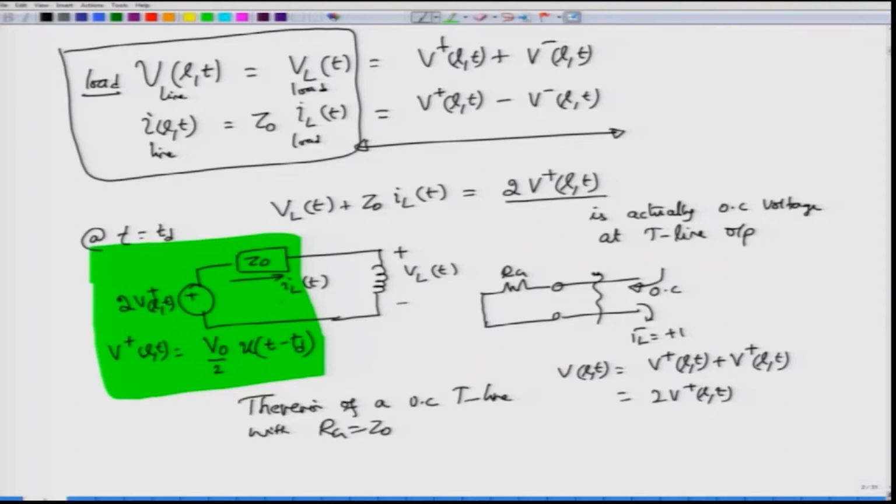How do I do that? Well, this is an inductor. What is the relationship for an inductor in terms of the voltage and the current? For an inductor, we remember that if VL is the voltage across it, IL is the current through it, and the inductor has a value of L, inductance, measured in Henry, then the voltage VL will be equal to L dIL by dt. So I can substitute this expression for VL of t, IL of t.